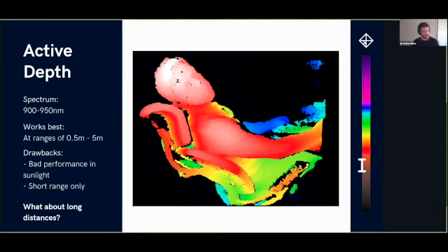Well, I have in my hand an L515 from Intel. I can tell you it works pretty damn well. The depth I get is beautiful. And that couldn't always be said for things like the Kinect. For instance, there was a lot of calibration you had to do, even on an academic level, to get that working the way you wanted. So I think it is probably moving towards time of flight, and I think for good reason. It's just simpler mechanically, and it gives just as good results. So yeah, that's a good point.